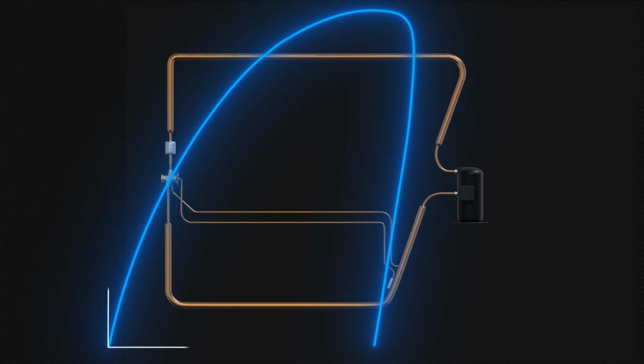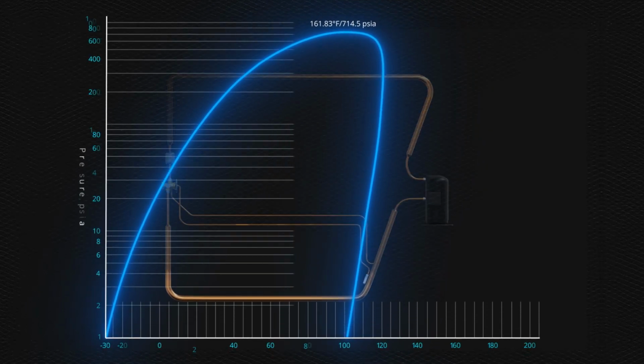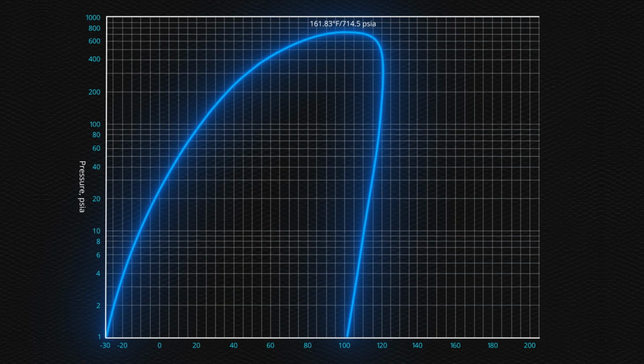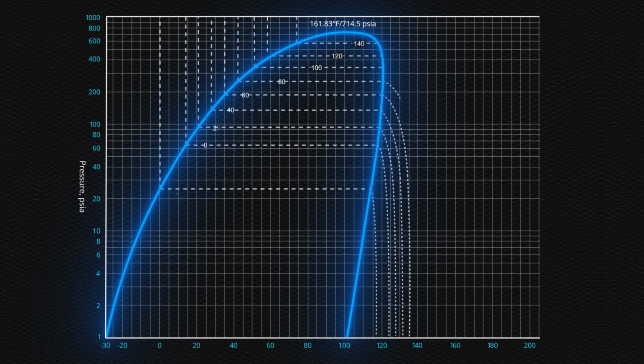The pressure enthalpy diagram is a tool for refrigeration engineers and designers, but it is also a useful tool for illustrating the refrigeration cycle. The pressure enthalpy diagram shown is a version that has information missing. The objective is to gain a general understanding of how the pressure enthalpy diagram can help technicians analyze the refrigeration cycle and how it can be used to improve refrigeration diagnostics.